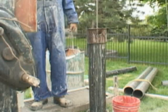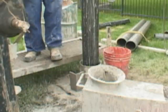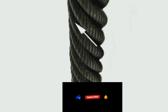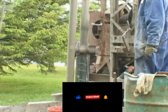The driller must then remove this mixture with the bailer, which consists of a hollow tube and a dart valve. The drilling cable supports the entire weight of the drill string assembly. The drilling cable is unique in its left lay construction. This unique feature imparts a clockwise rotation on the drill string during the up and down drilling process, ensuring an efficient cutting action and a straight, true borehole.